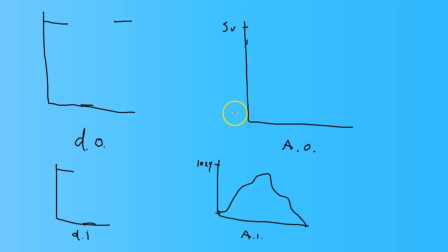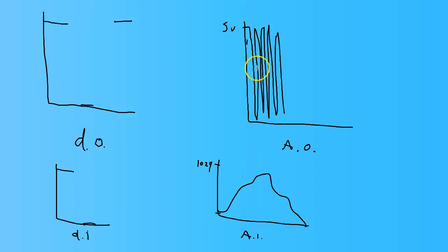But in some cases we can simulate that using this process called PWM, which basically turns something on and off really fast. Okay, and when you're switching something on and off really fast, the amount of time you leave it on in between is going to be like kind of like the percent that it's turned on.